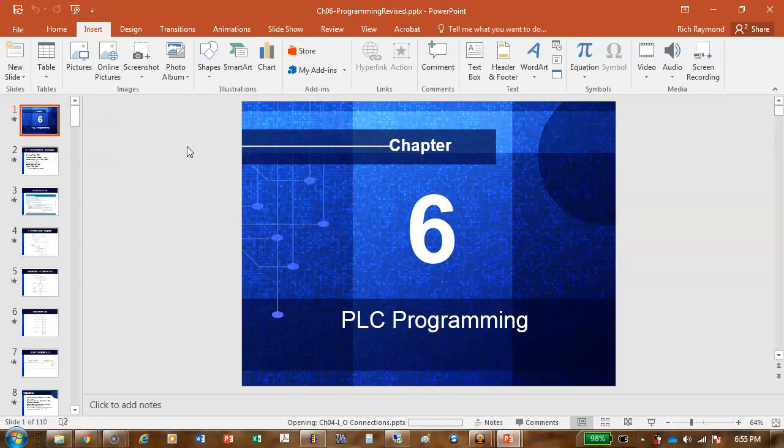And then when we upload a program, that's another term we have to learn, because it's the opposite of what you're used to. Your PLC is a computer, and your computer is a computer. When you're at home and you download something, you're bringing it from somewhere into your computer, but that's not the way it works with PLCs. Download is the term we use when we send the program from our programming application into the PLC. Upload is when we bring the program, or information, out of the PLC and into our application. So that's backwards from what most of y'all usually know.